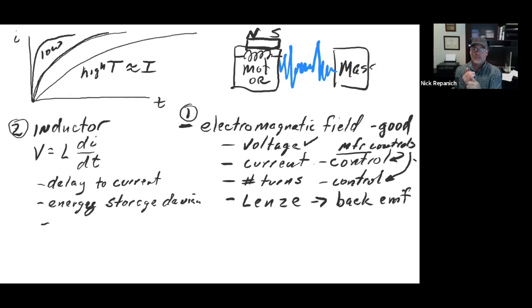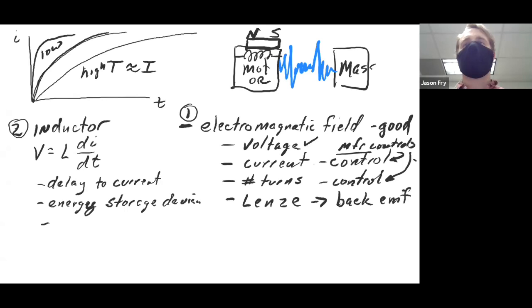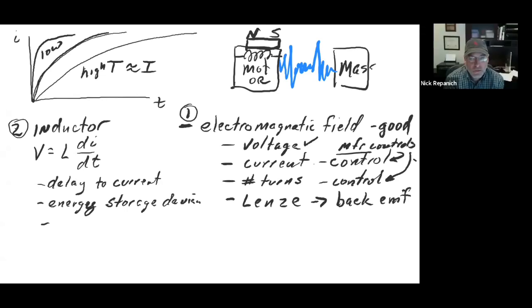But you got to pay attention. So what is an 1800? It's always the 60 in there. So an 1800 RPM motor is really what revs per second? Math in your head? 30. 30 revs per second. And how fast are we going? 1.5. What's your spec? 1.5. Right. So you have a high torque, low speed application.